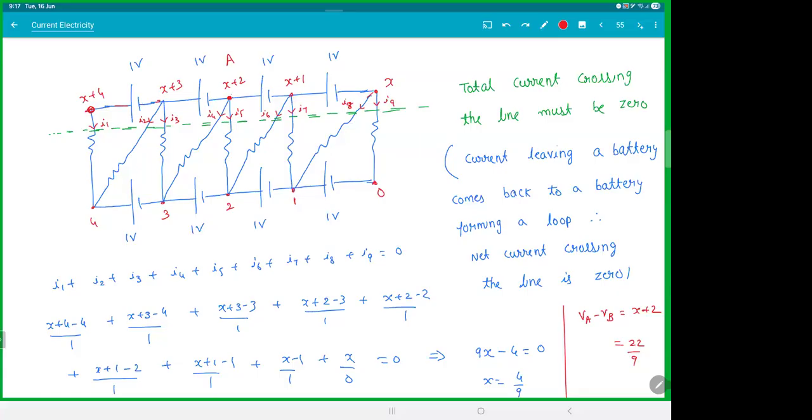You can apply nodal analysis not at a single node, but you can take 10 nodes together and apply nodal analysis for all of them. And it should still work because nodal analysis simply says entering is equal to leaving. Is this making sense? Now, if you do it this way, it looks easy, right? Now manageable, but frankly, you should have seen this before. If you have seen this before, it becomes easy in the exam. Any doubts on this?